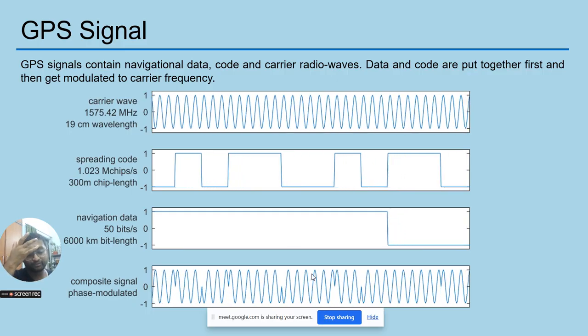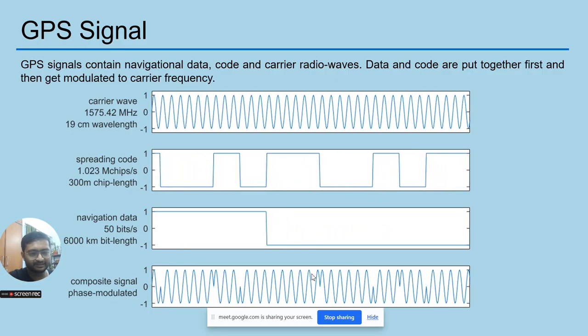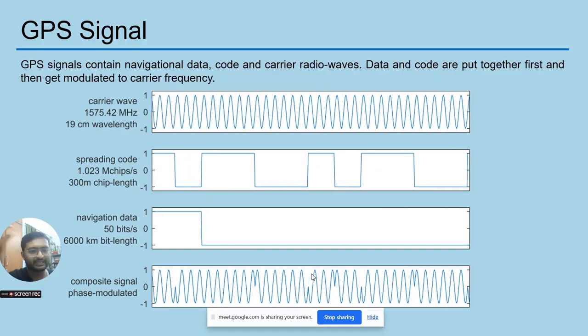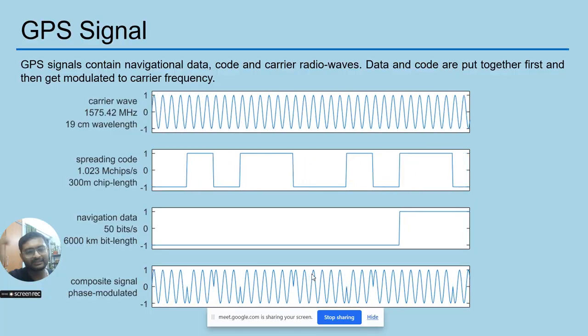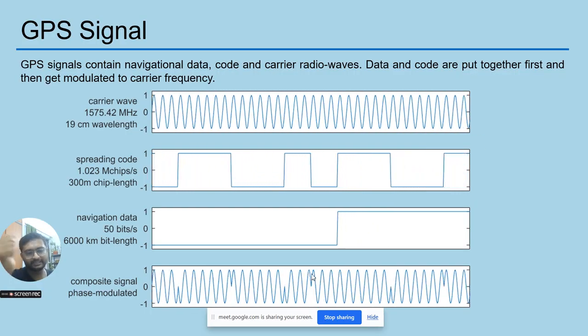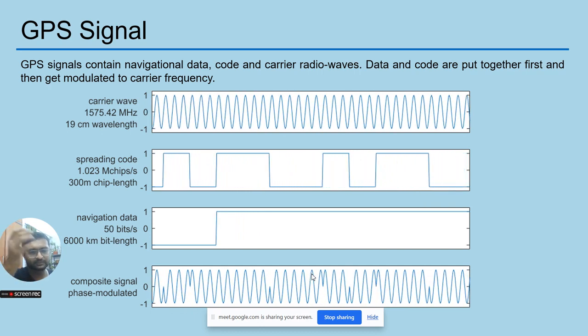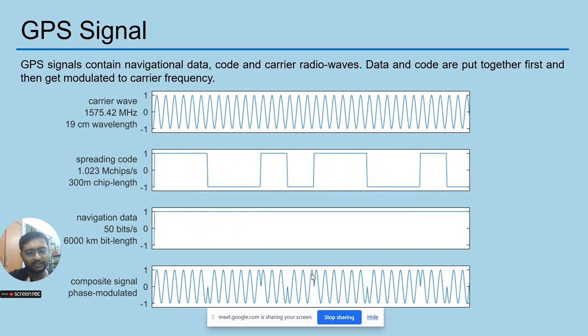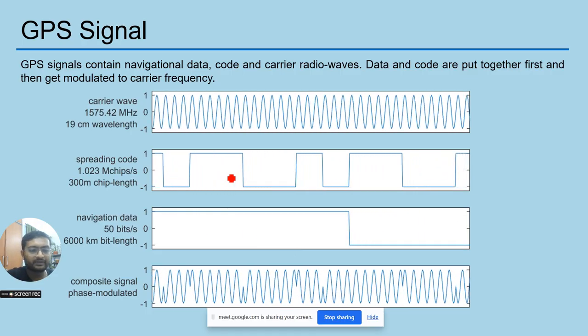Now when you take any GPS data, it will look something like this. It is a kind of signal. First is a carrier wave, which will carry the signal coming from the satellite. Then there is a spreading code, which will spread the data so that it does not get mixed, which is the C/A code and P(Y) code. The carrier waves are L1 and L2.